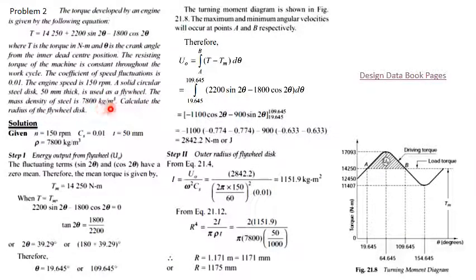So already we have the value of r, and putting it in this equation, we get v. Now as the peripheral velocity and density are known, putting these values in the equation, we will get the maximum radial or tangential stress in the flywheel. So here we complete the problem.